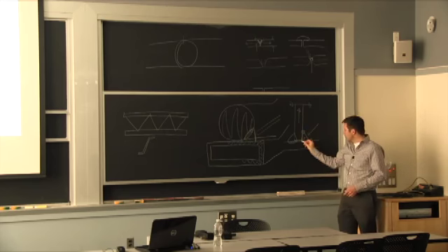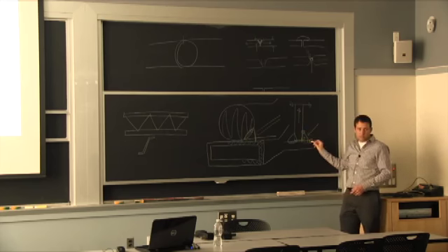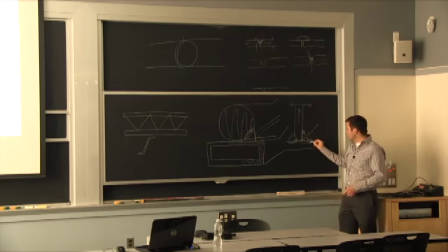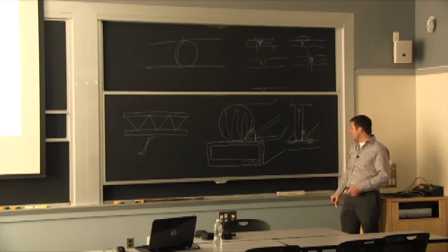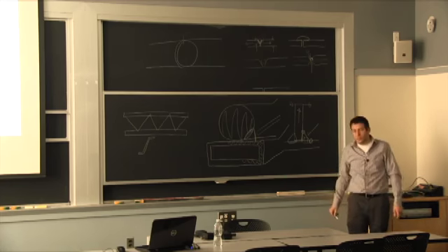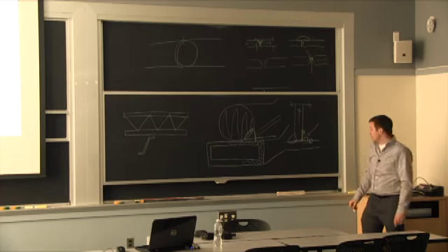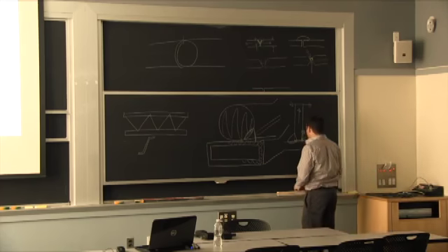So we call this the root of the weld, and this is the toe. You want to minimize the risk of defects at that toe, and the good news about that is it's easy to inspect. You can look at it visually and see if you have good fusion or not.